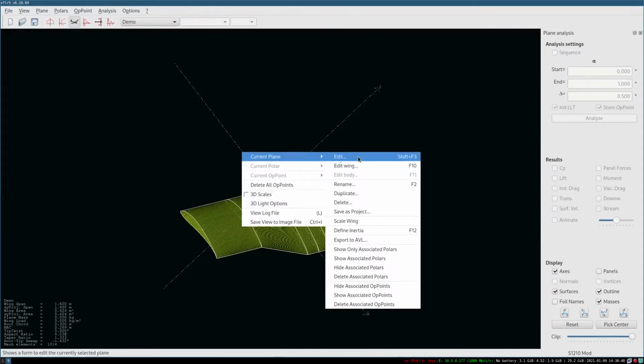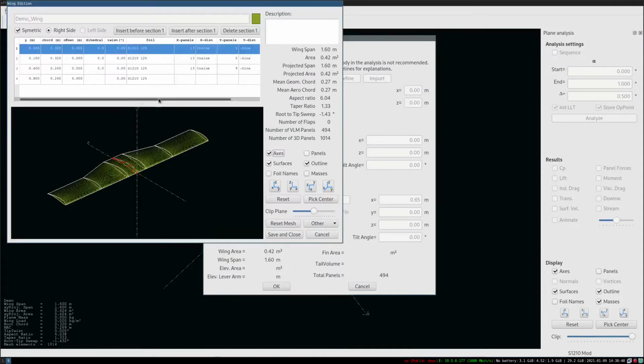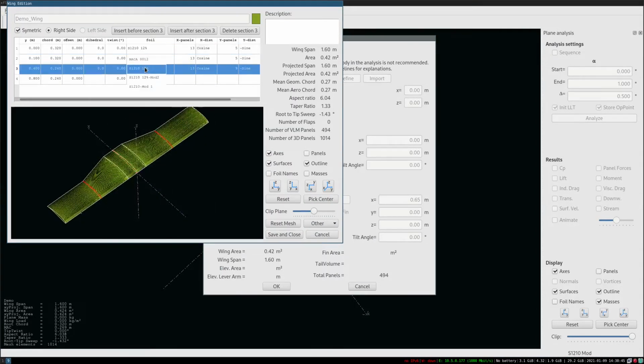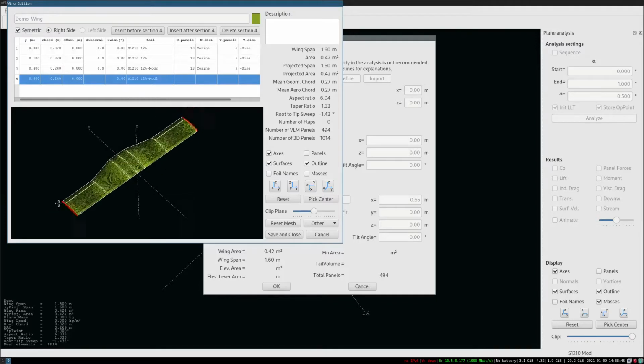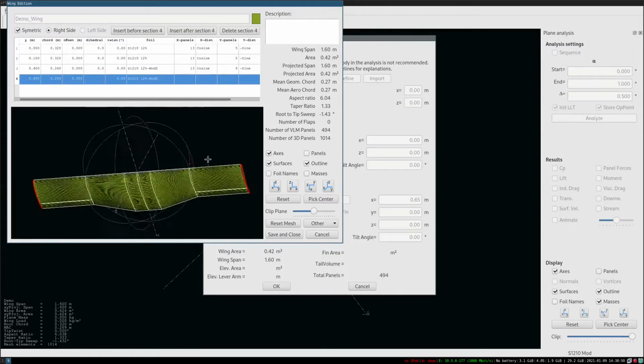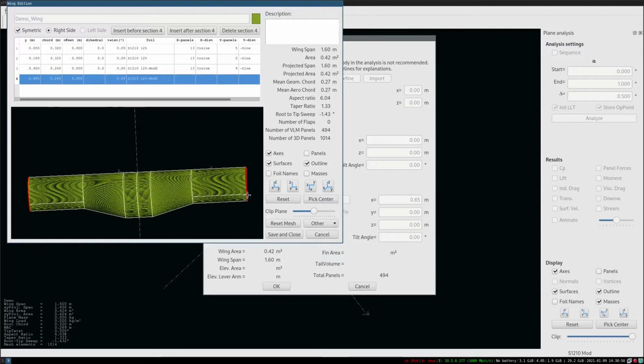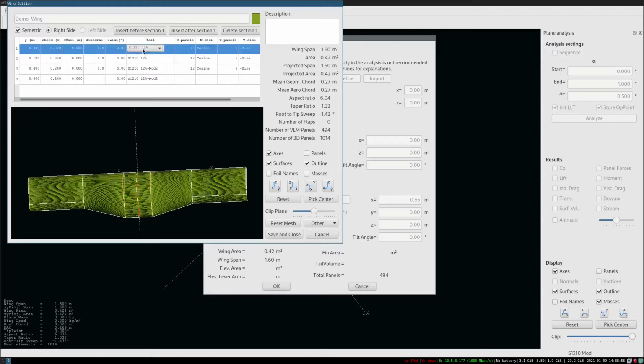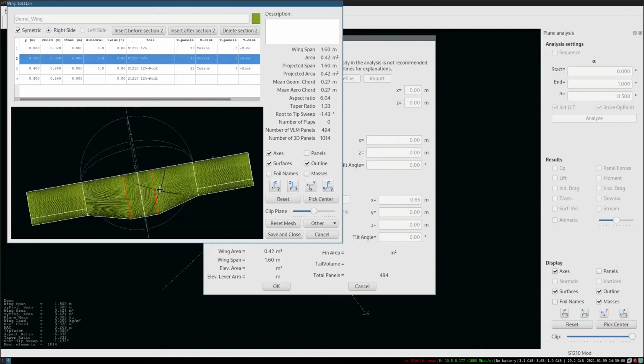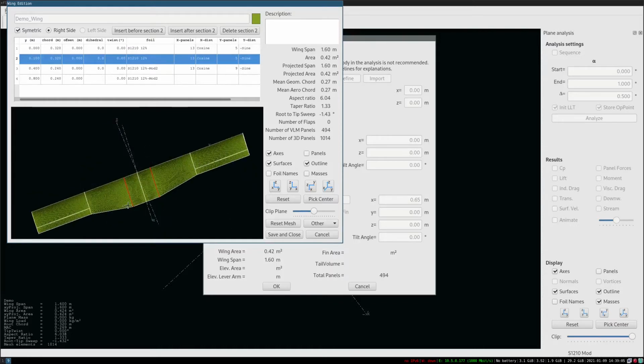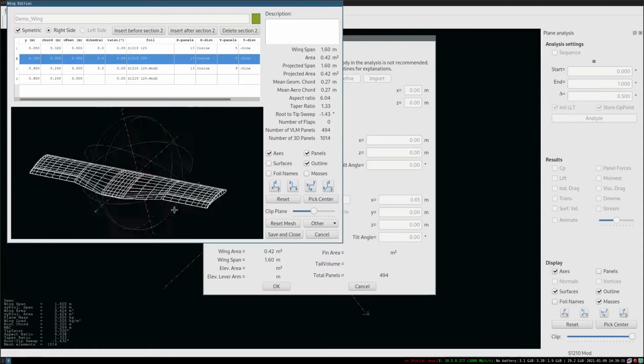And there is a key change now. When we go ahead and edit this wing, where you have a control surface, you actually need to define the aerofoil as the one with the flap. And you'll see here it actually draws in where the control surface is. One would say, why would you not just use the mod 2 everywhere? And the reason for it is you typically do not have control surfaces along the entire edge of your aerofoil. So that's why you actually need both. It's a bit of a faff, but that's how XFLR goes, and it's free and it's doing your work for you, so not much you can really complain about.